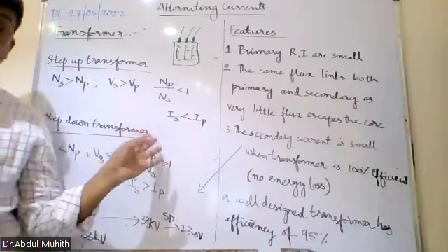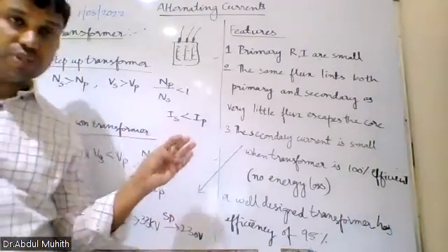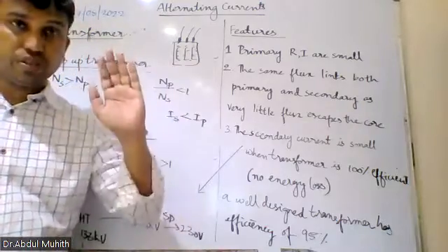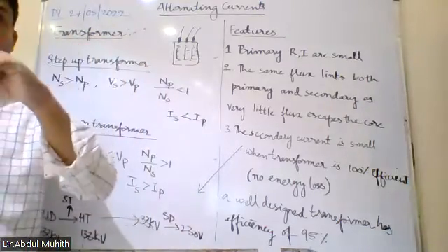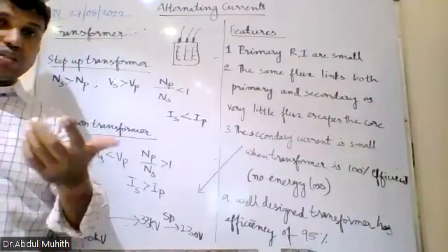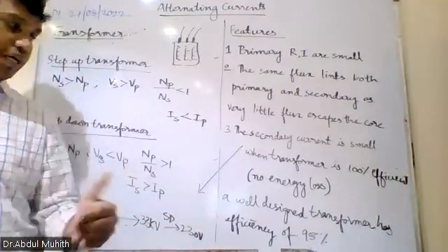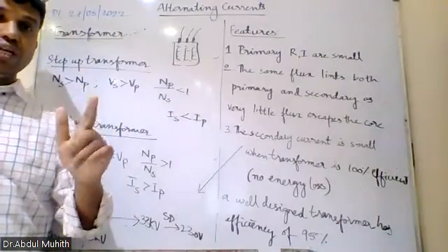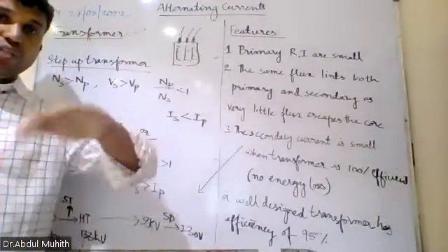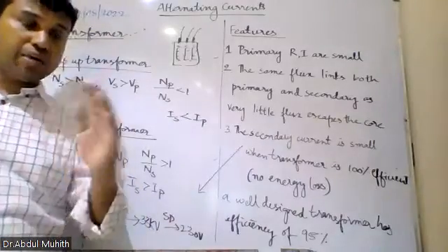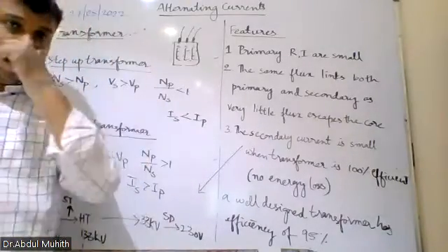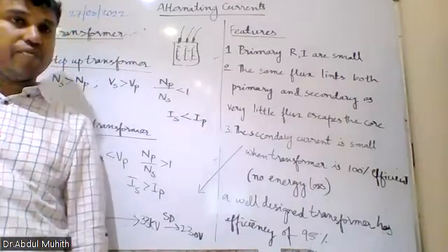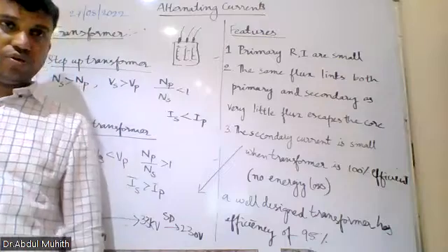The high tension tower wires we cannot directly bring down to our place. It's not possible, that is very high voltage. So those wires will go to the substation. From the substation the power is brought down and then given to the industries. First large scale industries, small scale industries, then it comes to the offices. It is a step down in sequence. That is why the industrial area is completely different. The cement factory is somewhere out in the outskirts, because the voltage supply for a cement factory is different.